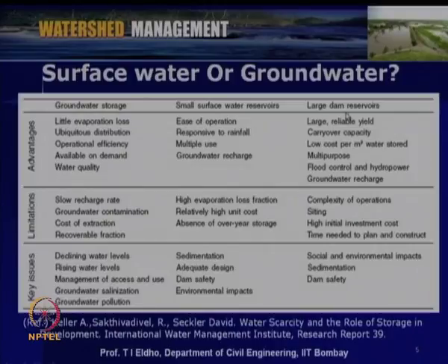And then if you consider large dam reservoirs, then the advantages are there. We have large storage, there will be reliable yield, then we can carry over whatever is available to the scarce months or the other seasons. Then low cost per cubic meter of water stored. Then of course multi-purpose we can go for, it is not only a source for water, but also hydroelectric power production and other multi-purposes. Then flood control and hydropower, then groundwater recharge. So these are some of the advantages of considering either groundwater or small surface water sources or large dam reservoirs.